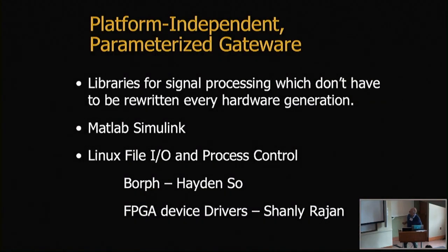One of the big things is not about hardware. We used to build a lot of hardware in CASPER, but now there are a lot of companies putting Ethernet on their boards, so we're moving away from building our own FPGA boards and even our ADC boards. A lot of CASPER work is in developing libraries and tools to make it easy to build instruments. We want to make it platform independent, so if you compile a design for one board and then want to upgrade to the next board, you don't have to make a lot of changes.